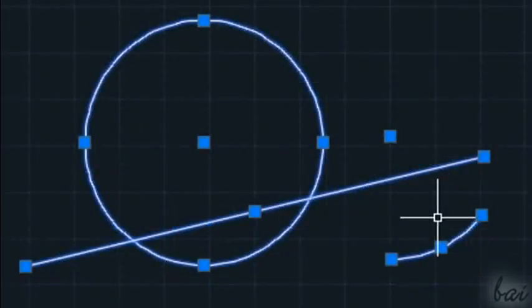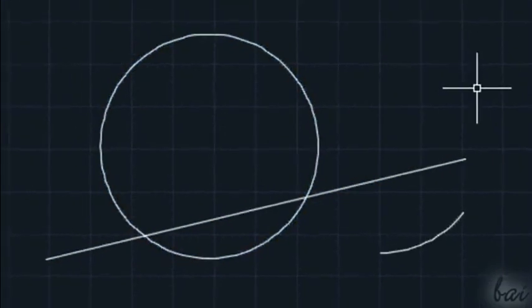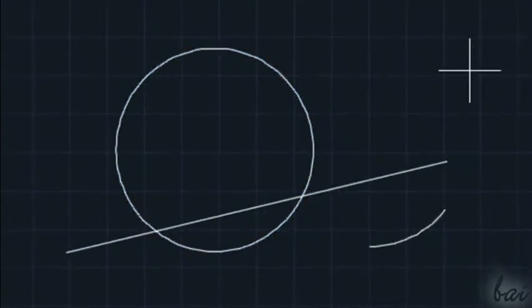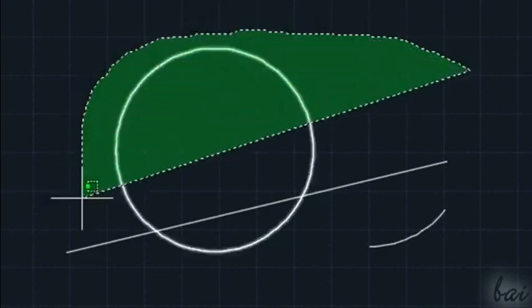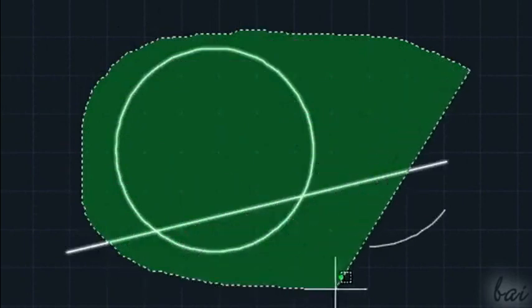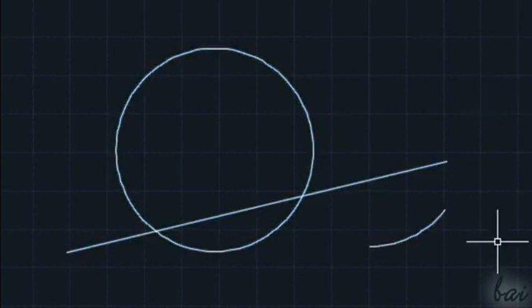You can remove objects from your overall selection, clicking on them while holding Shift down. In this case, a small minus sign appears next to your pointer. Otherwise, you can click and hold your pointer to create a personalized selection area. Any object that touches it will be straight selected. As always, press Escape key to undo all selections.